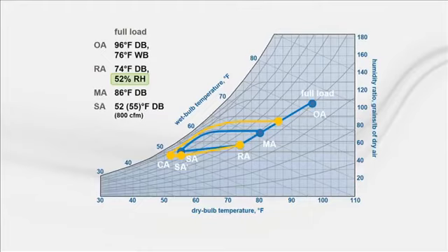A cool reheat system uses energy. It requires more cooling energy to cool the air, and it requires reheat energy, recovered or generated, to heat it back up. Alternatively, there is a desiccant option that can reduce the air handler dew point while reducing energy significantly, a type 3 desiccant. CDQ, the name we use for our type 3 desiccant solution, requires a little more explanation.